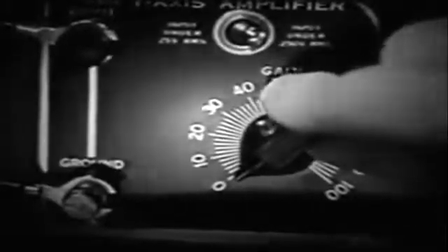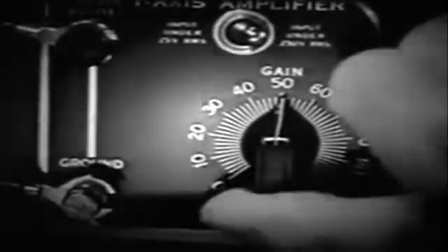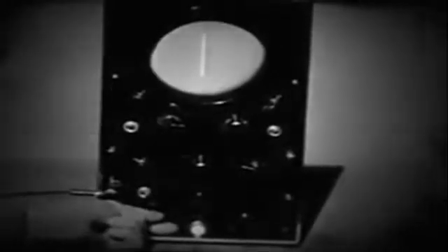Through these terminals, the signal passes to a simple voltage amplifier circuit. This amplifier, with variable gain control, connects to the cathode ray tube deflecting plates. The gain control on the panel permits us to expand or contract the vertical line of light. The horizontal amplifier circuit is fundamentally the same as the vertical. When we apply AC voltage to the horizontal deflection circuit, we can expand and contract the horizontal line.